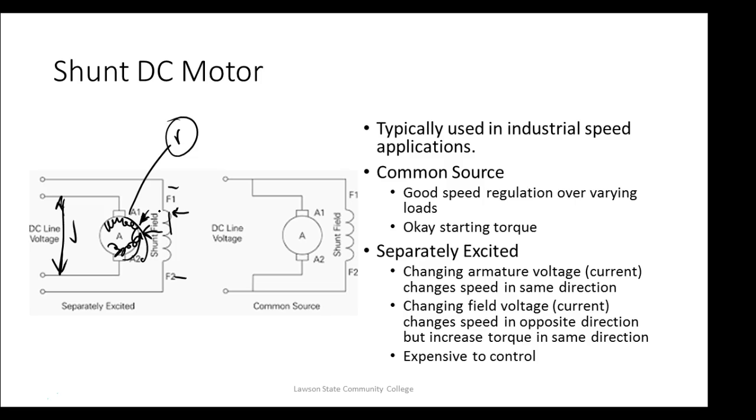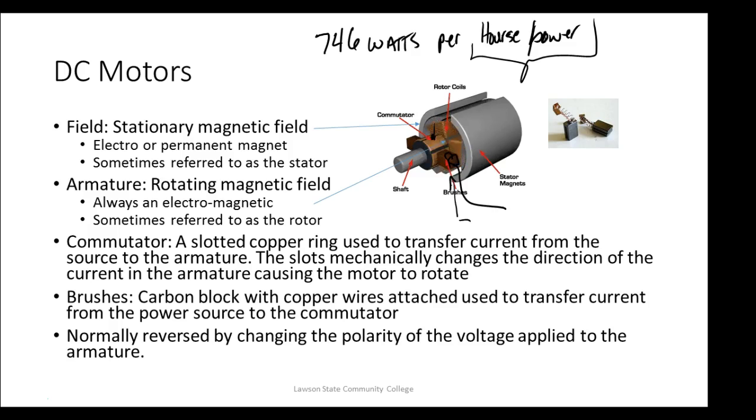The stationary field, right? So we always got to have a stationary field, and then we got to have a what? A rotating field. And then somehow we gotta switch them, right? You understand? What's nice about AC, it automatically switches the field. DC don't do that. So what do we have to do on a DC motor? We gotta switch it with a what? With this thing called a commutator. So we let the motor itself switch the field. Y'all understand that? So the rotor itself constantly switches the field.